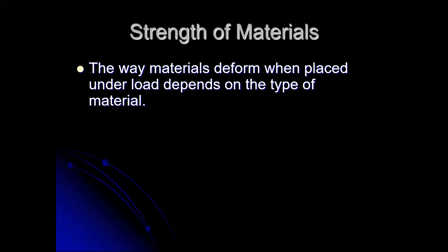We take samples of materials, and we take lots of samples, and we pull on them till they break. And we measure what the stresses are, and we figure out where those critical points are in the system, what loads make the material stretch out permanently or what cause it to break. And we do this for hundreds and hundreds of different samples, and we average the results. So we get an experimental measurement of strength. And that's what we'll look at first here, the strengths in tension.